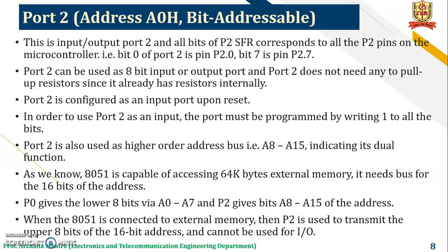Now port 2 has another function: it is used to send the higher order address bus, that is A8 to A15. It's a dual function. As we know, the 8051 is capable of accessing 64 kilobytes of external memory. It needs a bus for the 16 bits of the address.